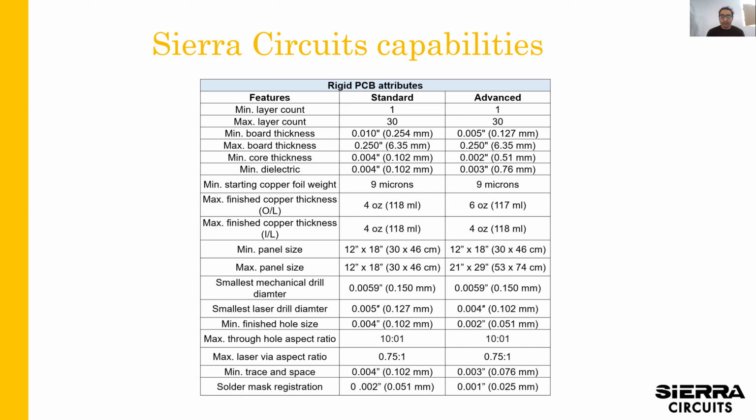It's also, can you plate that via, can you clean that via and then plate it so there are no hole wall defects, which is what I alluded to earlier. So taking one of these capabilities and assuming it to be 100%, that you can follow it and there are no issues, is not the right way to go.